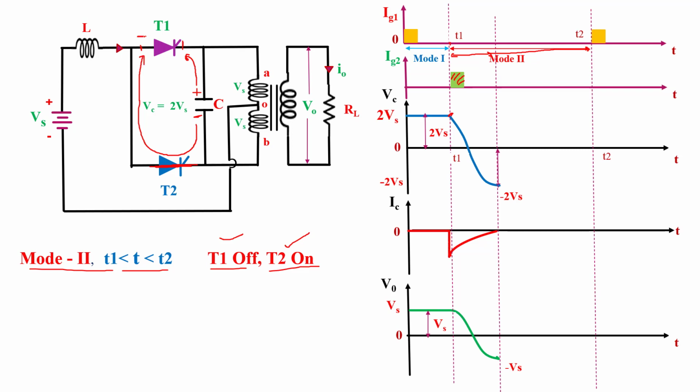So that will make thyristor anode negative with respect to cathode, and we know that when anode is negative with respect to cathode in case of thyristor, thyristor will be turned off and behave like an open switch. So due to this capacitor polarity at time instant T1, this capacitor will turn off the thyristor T1, and there is no current flow across thyristor T1.